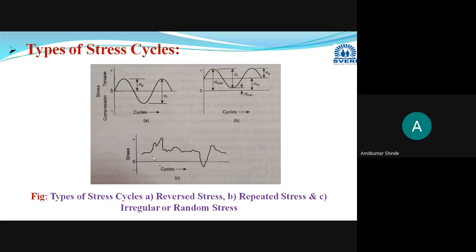In short, in the rotating components, failure occurs due to fatigue only. And this fatigue is caused by the fluctuation in the stress values. The next step is how to check the fatigue strength, or the fatigue limit, or, as some books mention, the endurance limit.